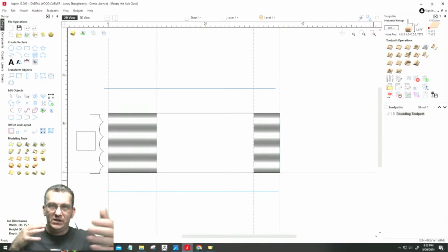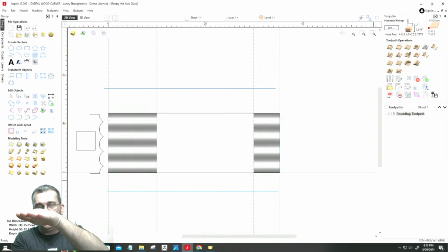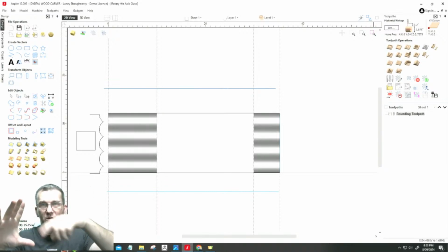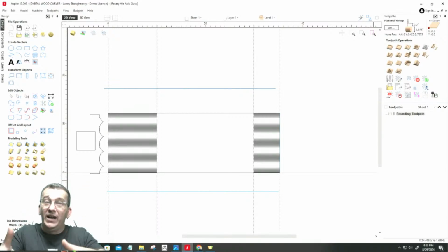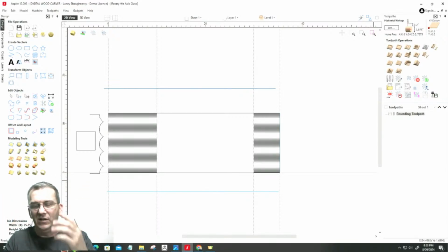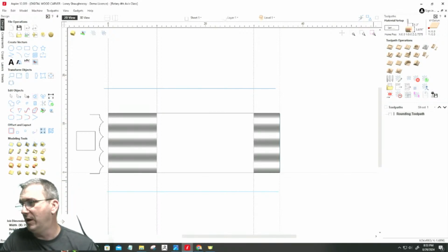You can mount it either way. So the length depends on your carving area, but also about 8 inches in diameter by default. But if I elevate the center point of the 4th axis on those machines, I can raise that center height. Let's say I raise it from a 4-inch center to a 5-inch center, then I could do 10 inches in diameter, right? So I just have to elevate to get that extra height all the way around. And I can do that with the 2636, 3648, 4848, and 5100. So good question, Ronnie.